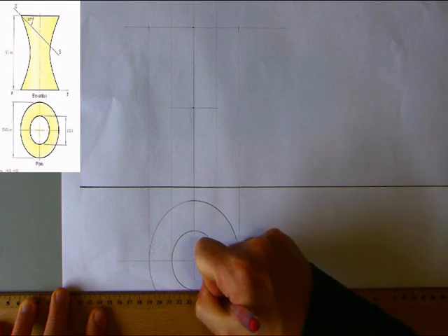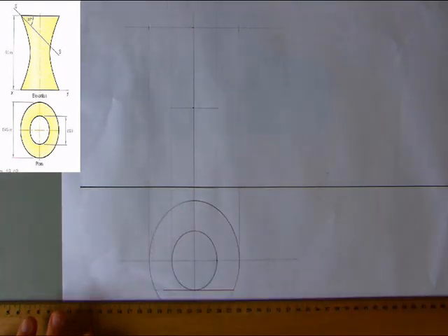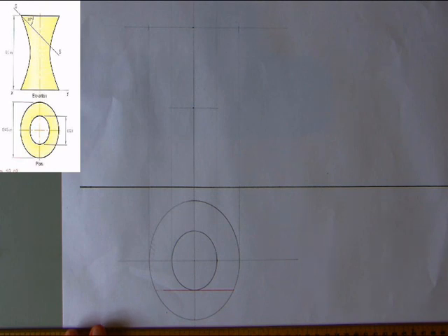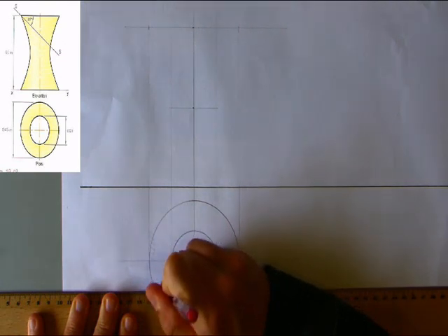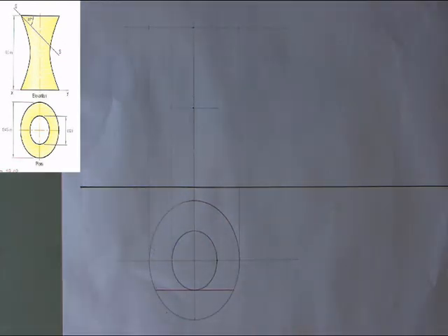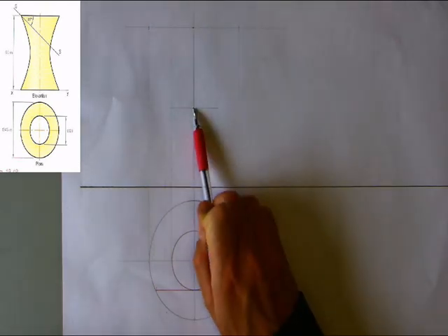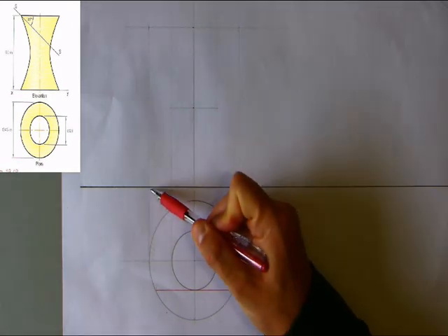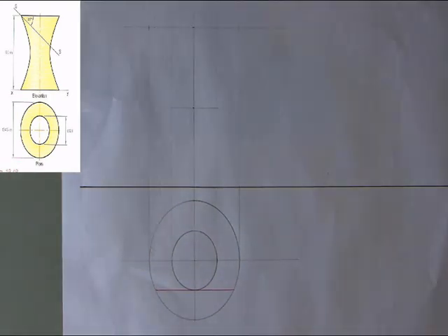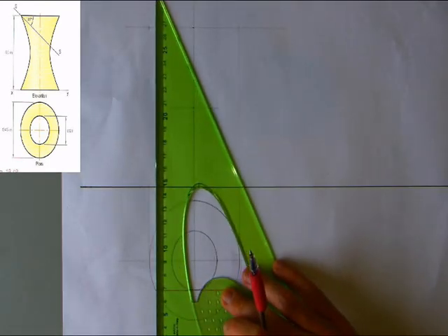So I'm taking this plan view and slicing straight down vertically through the object and removing the front half. By removing the front half, we'll end up with two lines. This point here is on the base, and that line will contact the throat circle here and then touch the top circle here. That's known as an element. It's a known line that will stretch from the base all the way through that center point and hit the top circle. So now we're going to transfer that in order to find it.